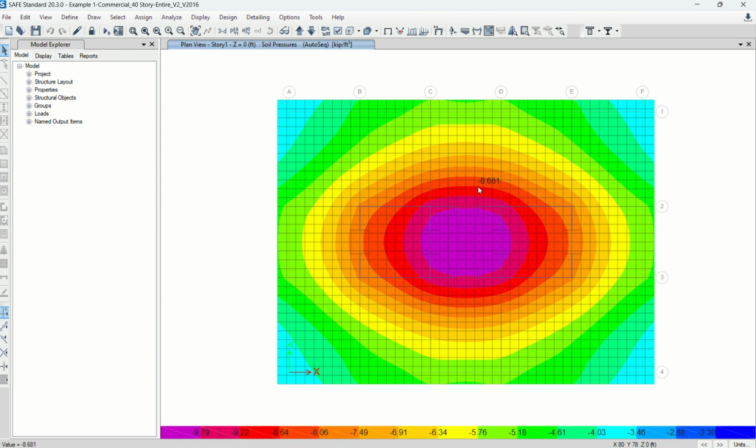After that, we're going to check the soil bearing pressure, set up some design strips and some load combinations so that we can design the mat and the reinforcement in both directions, X and Y. All right, I'm going to stop this video and upload it, and I'll continue with more detail on the mat foundation in the next video.